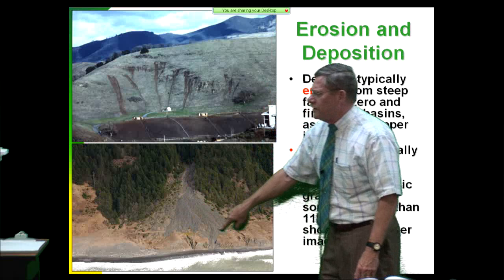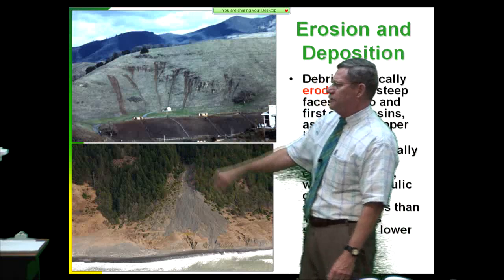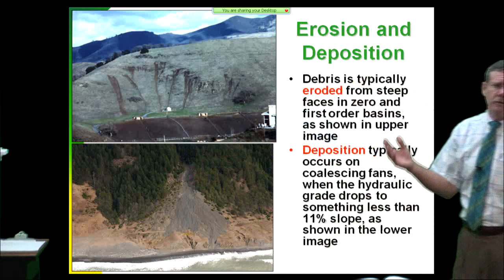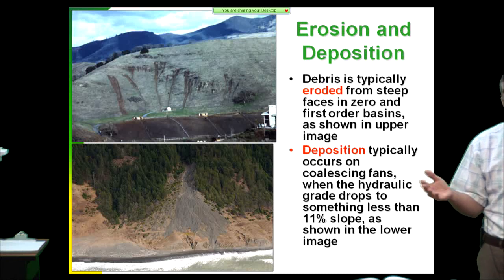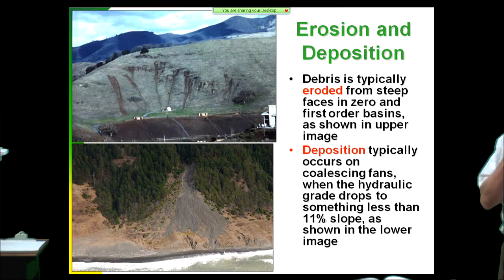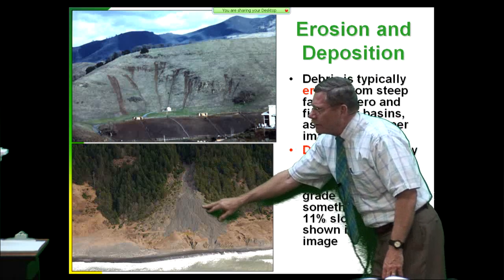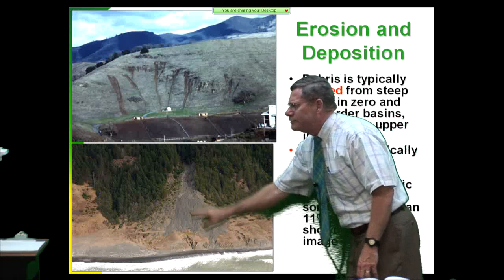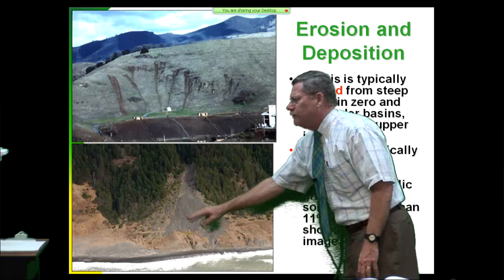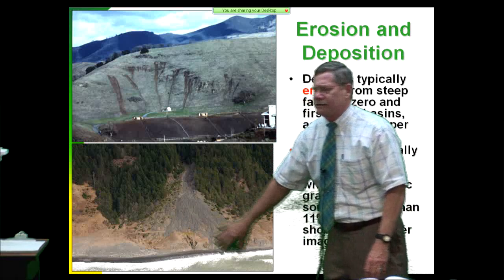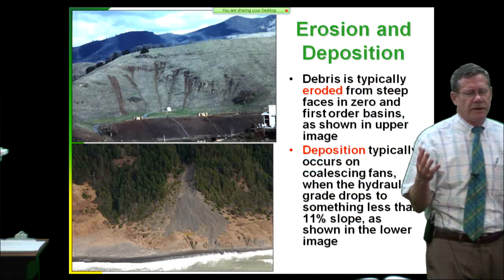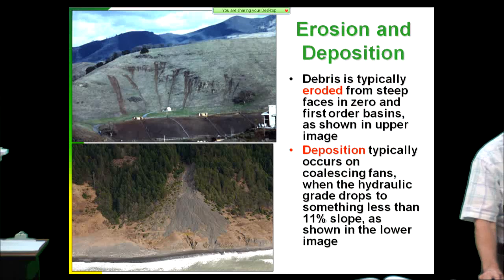So almost all the alluvial fans out in the western part of the United States, they're not alluvium. They are debris fans. And that material got there by debris flows. Then it gets reworked by water running over this later. So this will then have water run over it. But the way the big rocks get there is debris flows. Debris flows are what freight the large rocks.